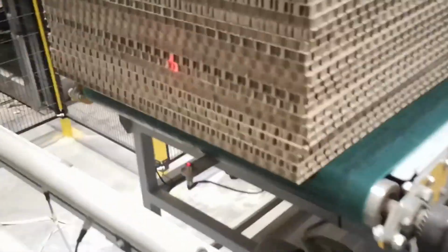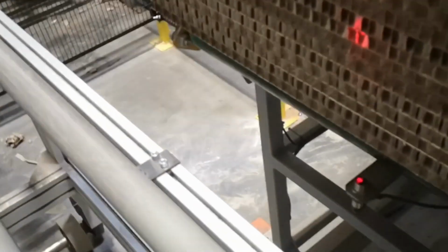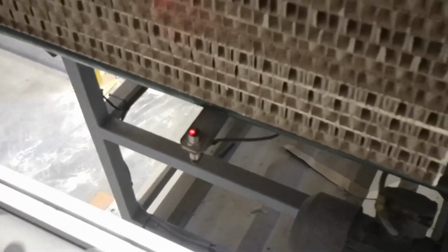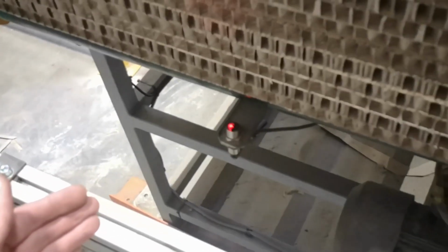So what does this trolley do? It goes to pick the product from this line or from this line. Also, I have a sensor here. In my program I have some parameters from which point I should start searching for the edge of this product, and where the start position and stop position are. And for this line I start searching for the edge at this point, let's imagine, and finish somewhere here.